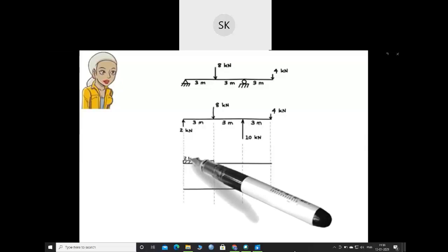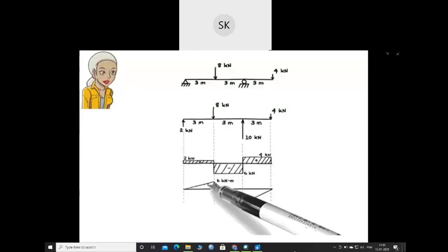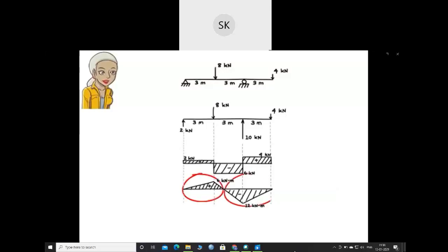If you are not sure how this is done without formulating the shear and moment equations, see lecture SA09. Note that the moment diagram has a positive region and a negative region in this beam. Therefore, the beam is going to deflect down in the positive region, like this. And it's going to deflect up in the negative region, like this.